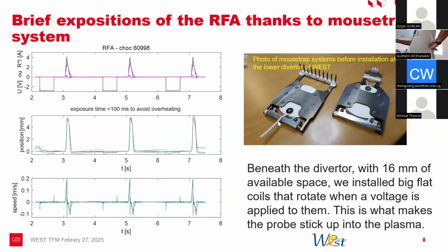And it's designed to make a vertical movement. It's a 2-degree rotation, which leads, given the lever arm here, which is about 15 centimeters, to a vertical movement of 5 millimeters. The probe is usually 3 to 4 millimeters below the surface. And when we put it in action, it can come up to 1 or 2 millimeters above the surface. And this is what makes it work.